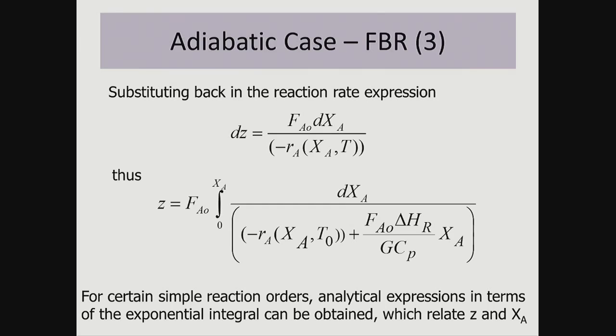So that is very familiar. That is additional for the heat effects, and what we're saying is built into that bit, because of the Z length, is the heterogeneous bit. So you've just added something into your plug flow tube, but the basic equation is the same. Okay, so that's the shortcut, and that's the one everybody likes to use because it's the easiest one to do, adiabatic. Why? Because you don't have to control anything. You let it do its own thing if you've designed it right.